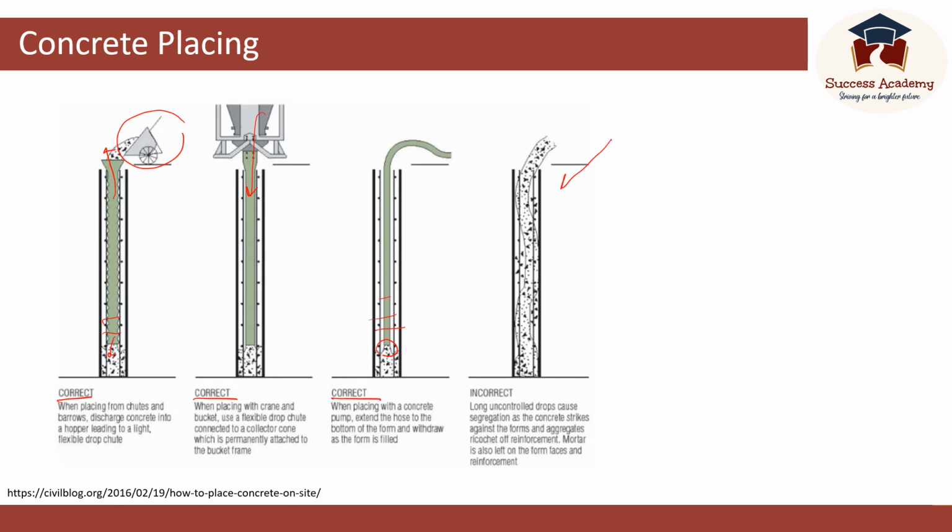And this is an incorrect way of filling concrete, where we are just adding concrete into the column. In this case, concrete may not fill fully from the bottom to the top. So it is an incorrect way of placing concrete.